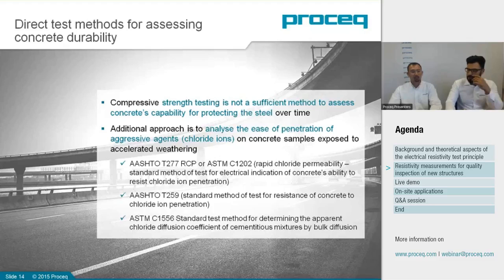Absolutely. Well, this was actually the first answer to the question that arose before. If concrete strength is not the parameter that I want to measure, then what? These are basically the three fundamental ways of testing, which are all based on measuring the ease of migration of a specific ion, basically chloride ions, by means of laboratory testing on accelerated weathered samples. And they're all electrical testing. So that was the first answer, and that provides a measure and then an estimate of the depth of penetration in a number of years. And that has become the base fundamental method to analyze durability.